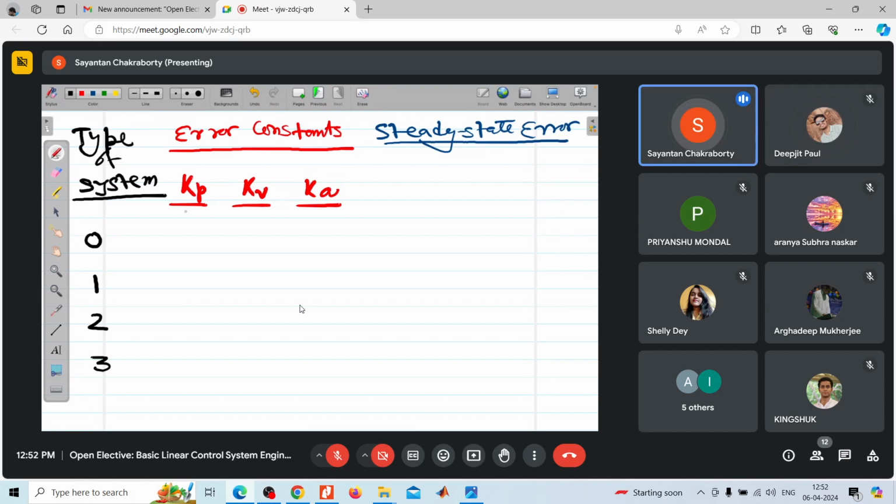The system will actually be a third order system. It will become a third order derivative of position. If you represent that, it will be a third order system containing 3 poles. But if you remember, all the performance indices and all these analysis tools are only limited to second order systems, right? So if it becomes a third order system, then it will give you an additional burden. Okay, I'll include that in the lecture.